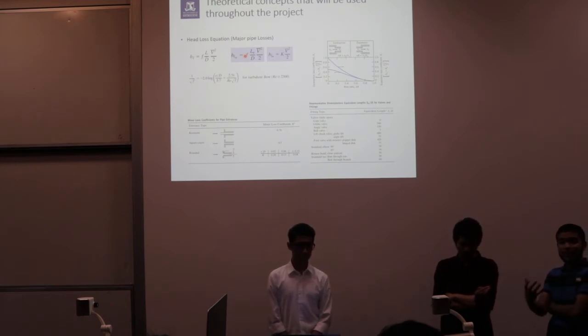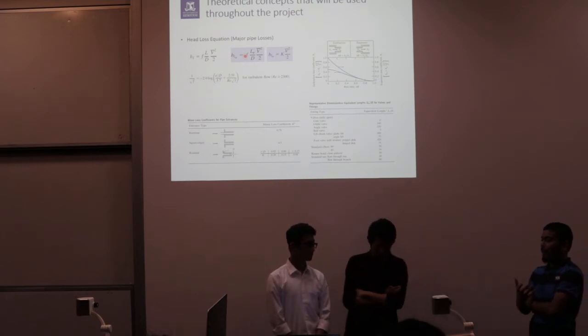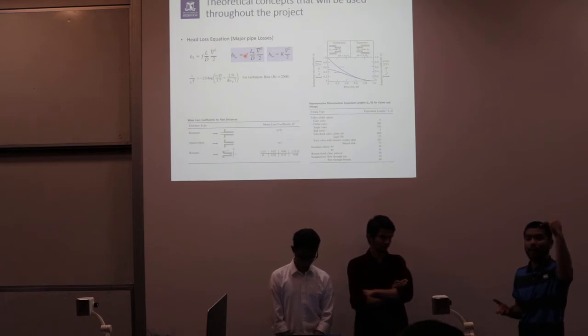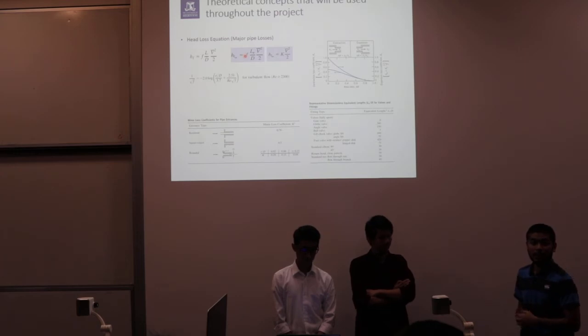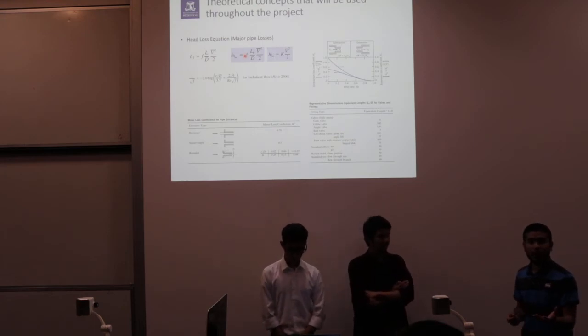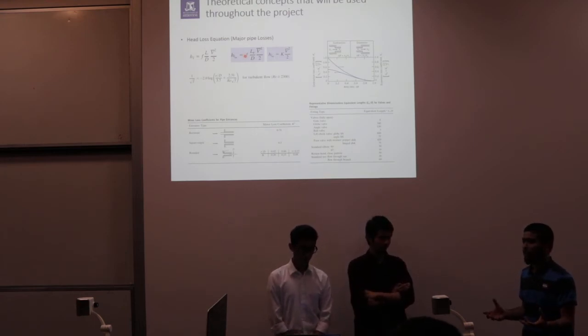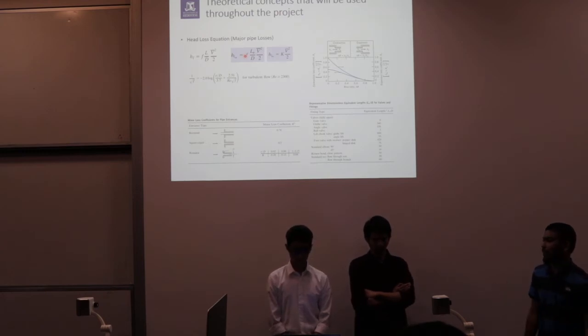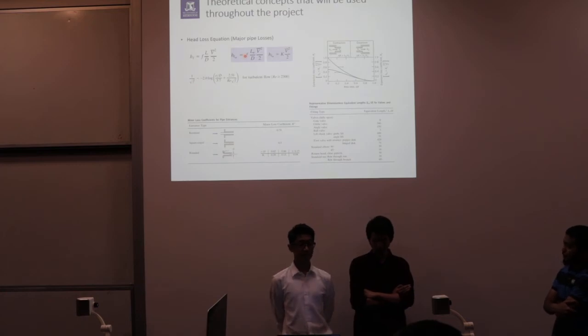So to compensate for this uncertainty, that's the reason why we have a control valve, and also what we did was we increased our head a bit more so we have a higher velocity, just in case the flow straightening device loss is much more than our estimate. There's no research paper that provides any way to calculate the losses of a flow straightening device. So what we tried to do is control the flow instead, to mitigate the issue. Alright. You have a question?